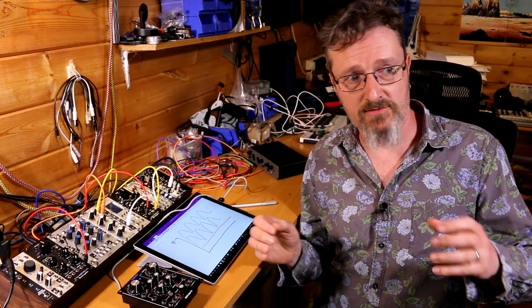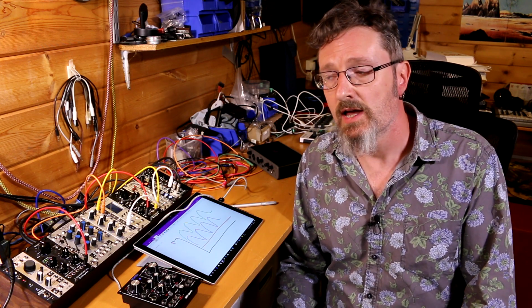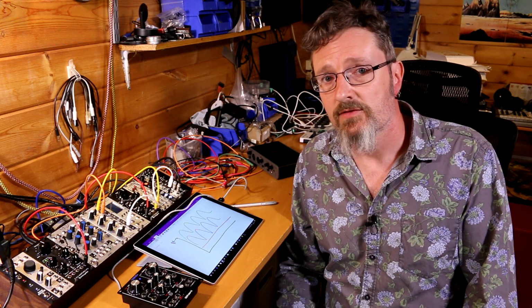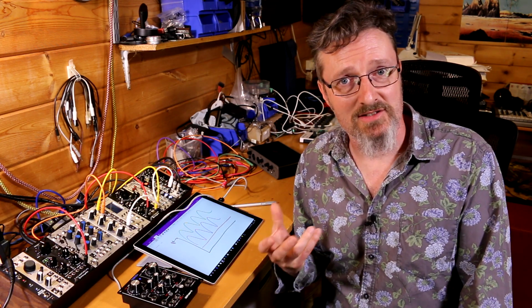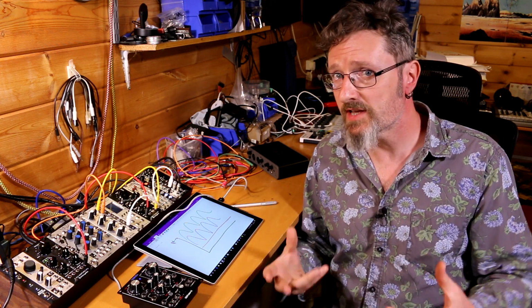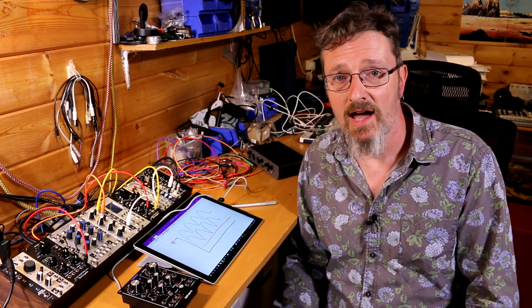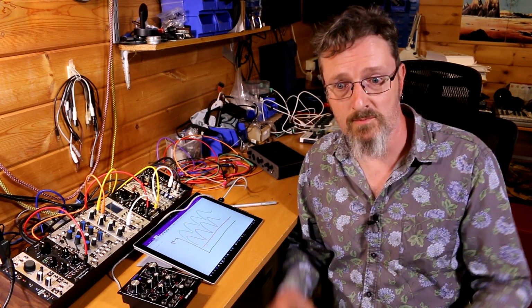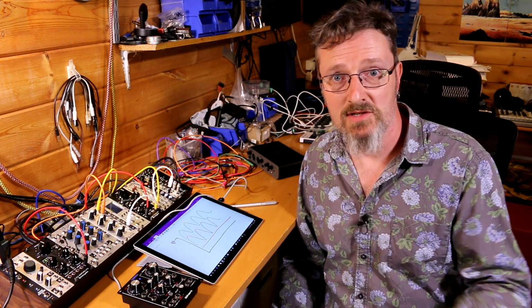Some of the RME ones do, particularly the headphone outputs, for some reason, tend to be DC coupled. Avid audio interfaces for their Pro Tools HD systems tend to be DC coupled also. Motu, a lot of their interfaces are DC coupled, although apparently, so I'm told, it's by accident, not by design, because they forgot to put the filter in. But all of these are quite big pro high-end audio interfaces, and I've struggled to find anything more low-end that I can use in a sensible way in my situation.